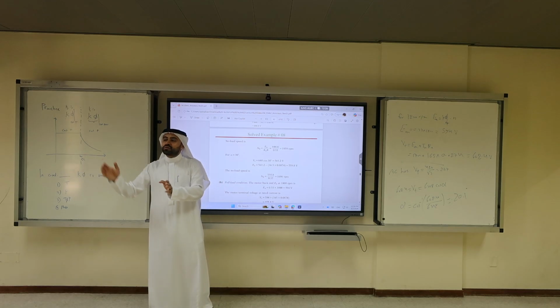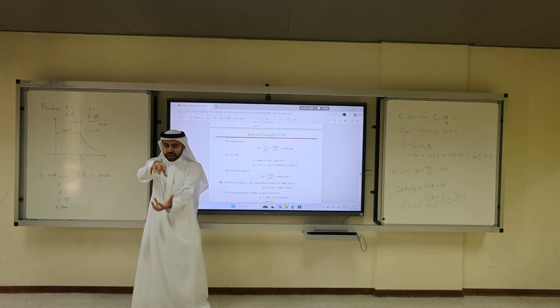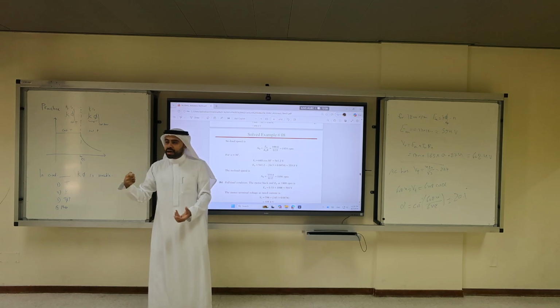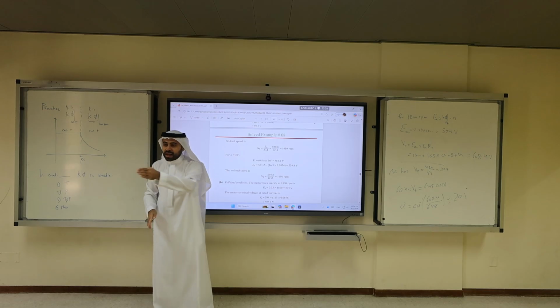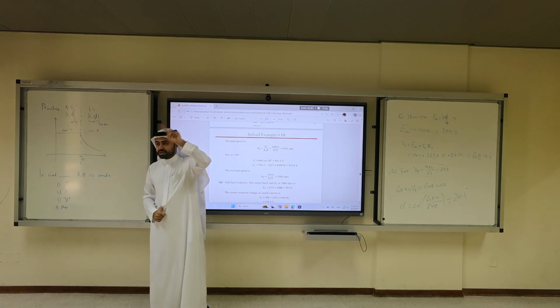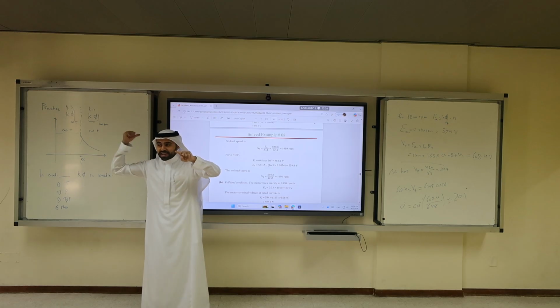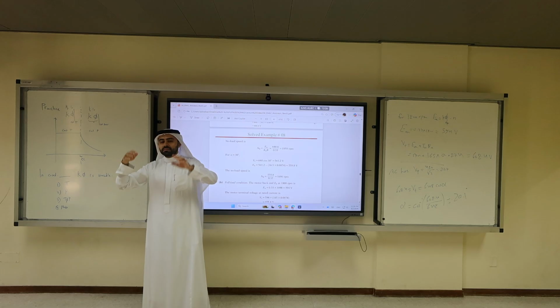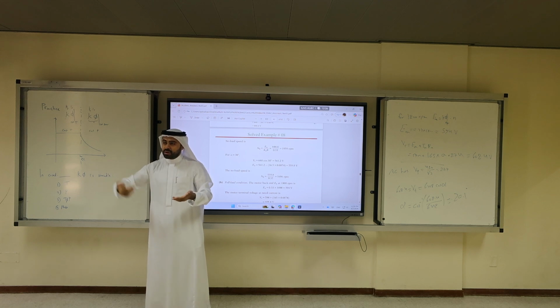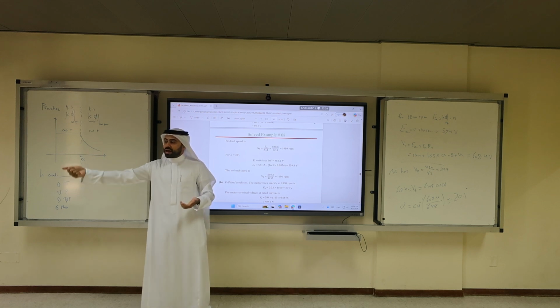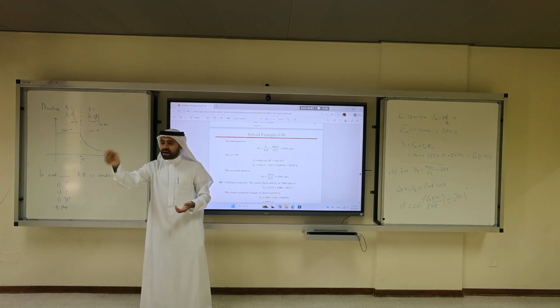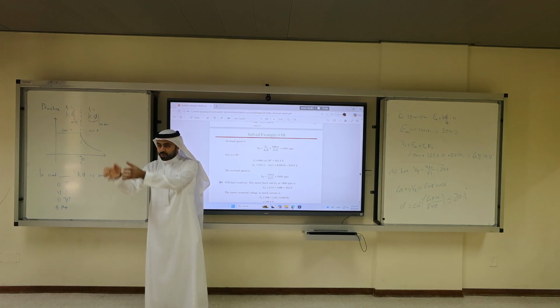Now I connected the load, full load. If I connect a mechanical load to a DC motor, it will draw more current, right? Because it draws more current, depending on my alpha, I can adjust the loaded motor speed. Before, in E360, when we were beginners in machines, we did not get into the source, it was just load or no load, two operating points. No, with the power electronics we have AC. Because we have AC, we adjust the speed using the firing angle of the thyristor converter control.